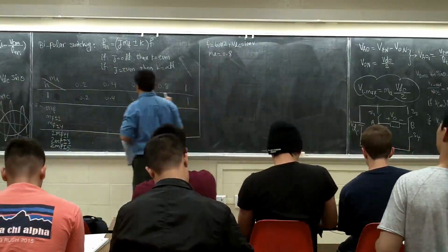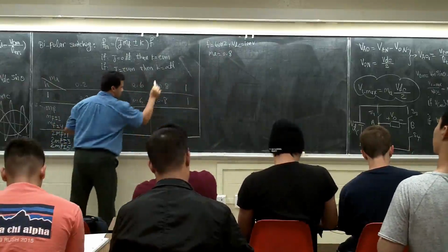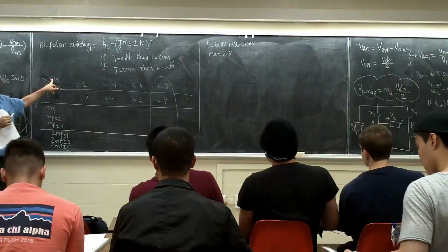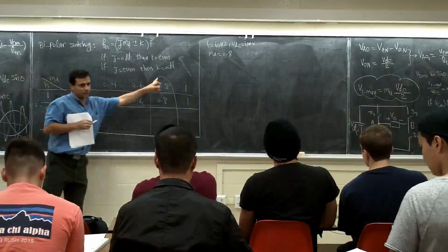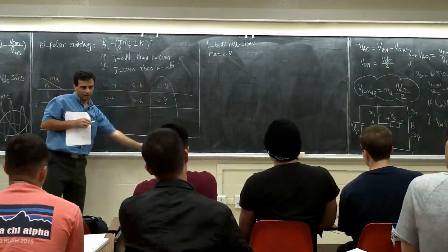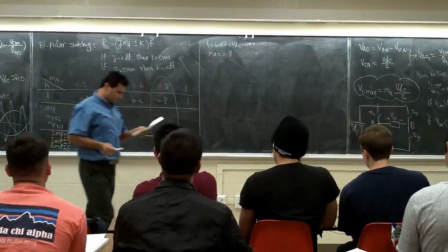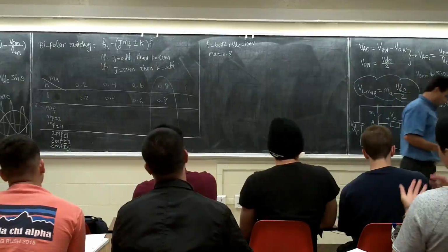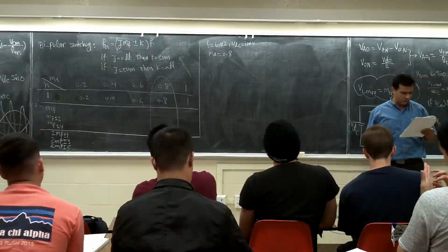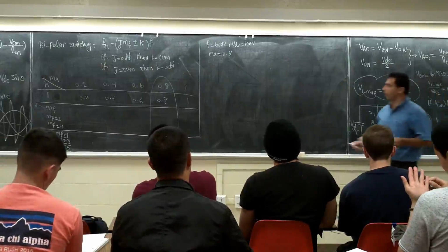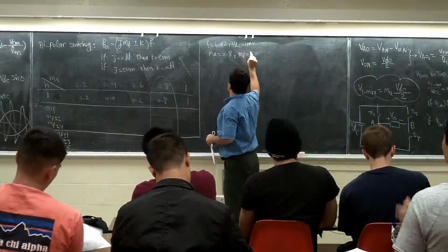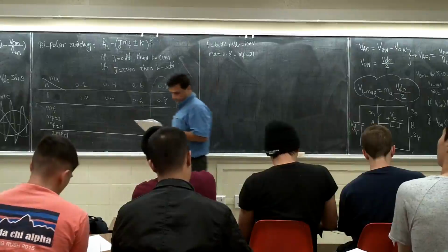So when you give us MA of 0.8, I'm going to use this column of this table, right? You look here, this is the MA. The amplitude modulation ratio MA is 0.8, and the frequency modulation ratio MF is 21. It's telling me MF is 21.